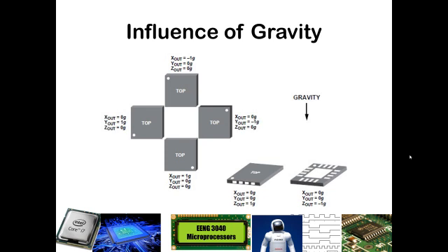So here is an example. We have a single accelerometer, and we can showcase it in 6 different orthogonal positions. If you see the position up here at the top with the dot in the top left, our x-axis in this orientation is going up and down, our y-axis is left and right on the screen, and the z-axis is in and out of the screen. In this position, our x-axis is experiencing 1g.